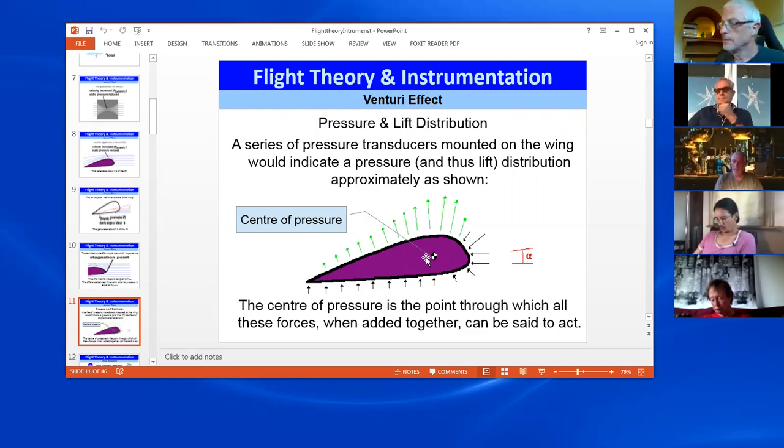But the main thing is that it's a principle you're operating with. Where is the center of pressure of the wing, and the relevance, which we'll come on to shortly, in terms of controlling the wing, is your position in terms of the center of pressure or center of force of where the wing is, and it's not constant. Depending on how the wing's moving, the center of forces will change. But it's just this idea of what is the center of pressure, and it's just an average of all these forces.